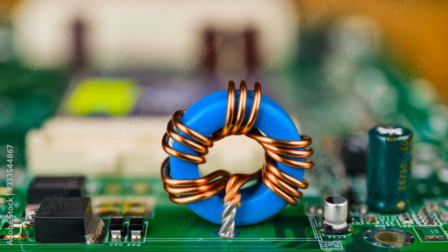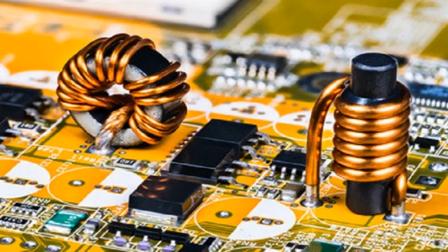Key points: Proximity detection. Inductive sensors detect changes in inductance caused by nearby metallic objects, making them ideal for proximity sensing. Non-contact sensing. Since the sensing is based on magnetic fields, inductive sensors can operate without direct contact with the object being detected. Robustness. Inductive sensors are resistant to environmental factors such as dust, dirt, and moisture, making them reliable in harsh conditions. Applications of inductive sensing with inductors.